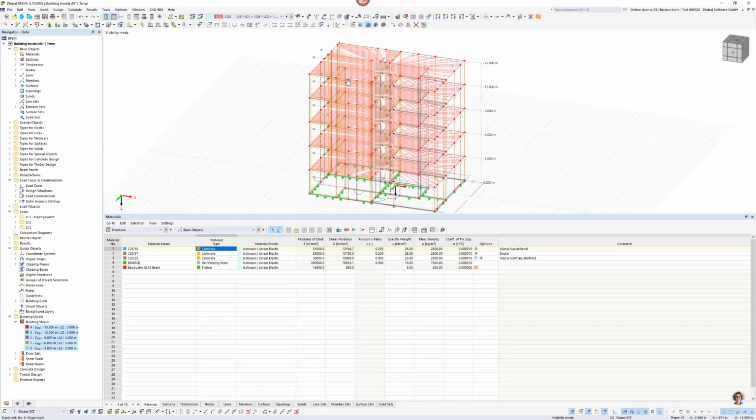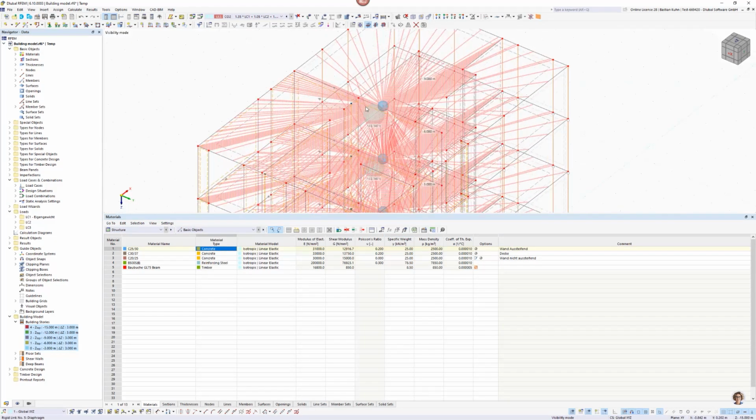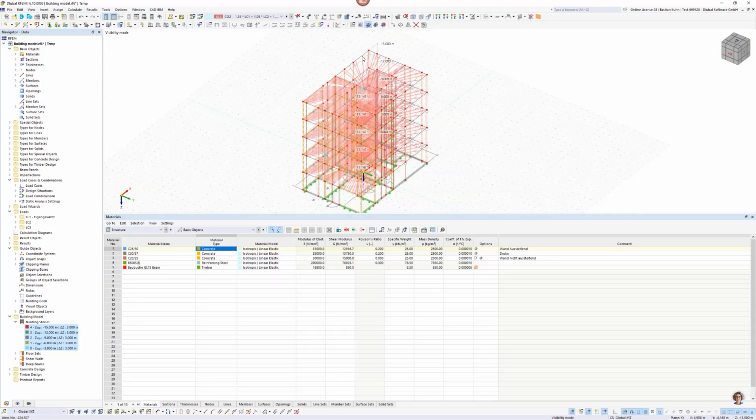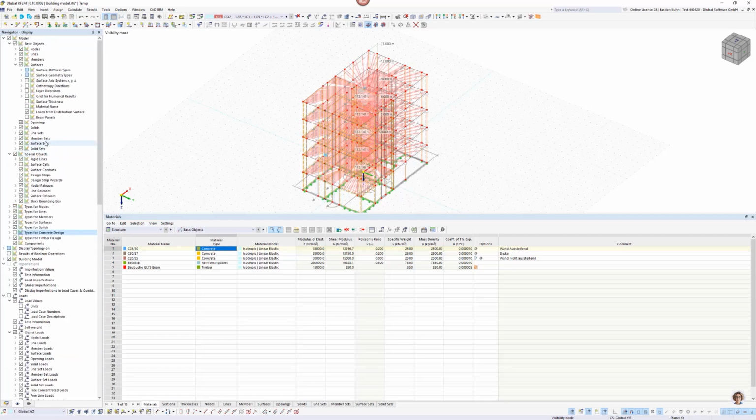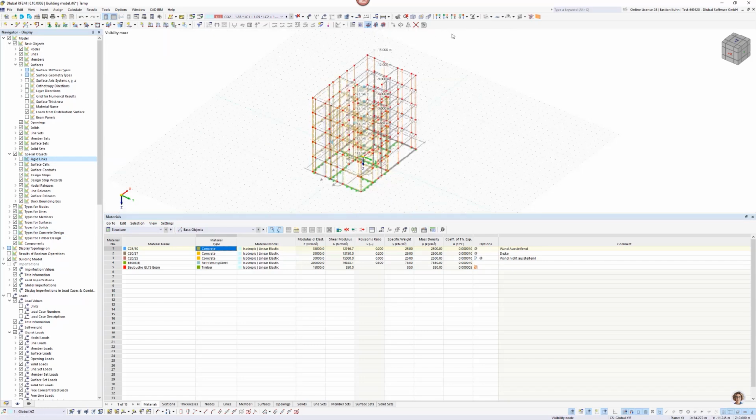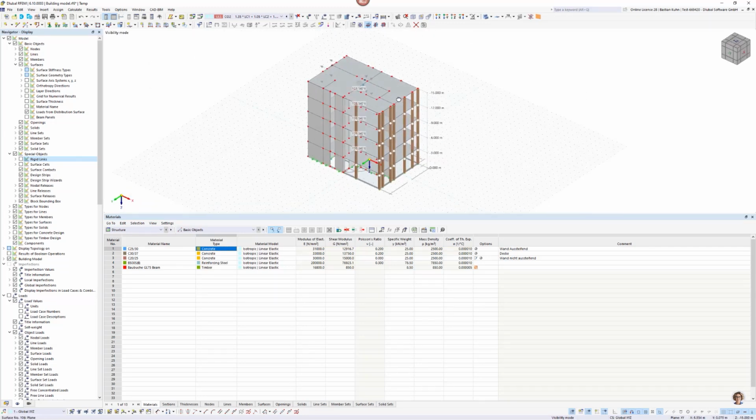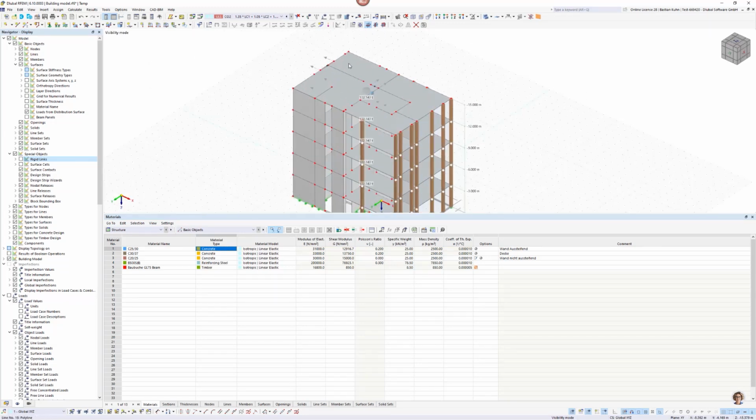And then from the mass center of the building model, to each FE element of my structure, a spider connector is defined, or it is named, hold on, rigid links inside. I will skip the showing of it because it's not so interesting, but it is important for the modeling.